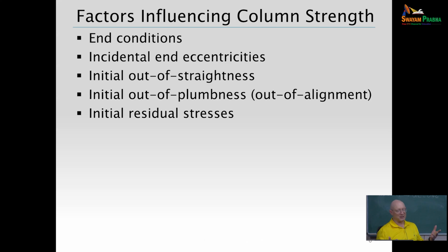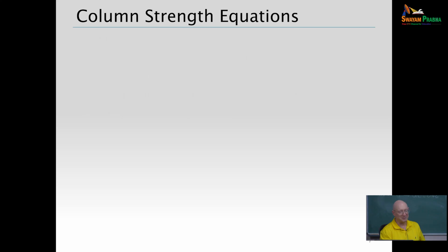Obviously, we know that any end restraint you have on the columns will influence the column strength. Any end eccentricities, out of straightness, out of plumbness, or out of alignment, and your initial residual stresses, all those things are going to impact your column capacity.